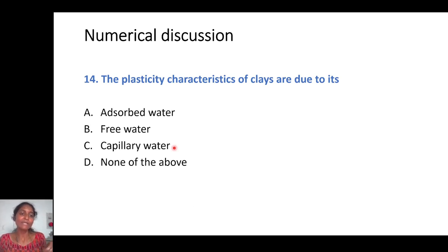This capillary action is just because the arrangement of sand or soil particles forms connected air voids, which creates the pressure difference from the atmosphere to below the soil. So whatever little moisture content exists, that tries to move to the top. This capillary action water can evaporate at any time. If you further add a little more water, that meniscus may break, and it is an unstable water. So this plasticity character, is it because of the capillary water or adsorbed or free water?